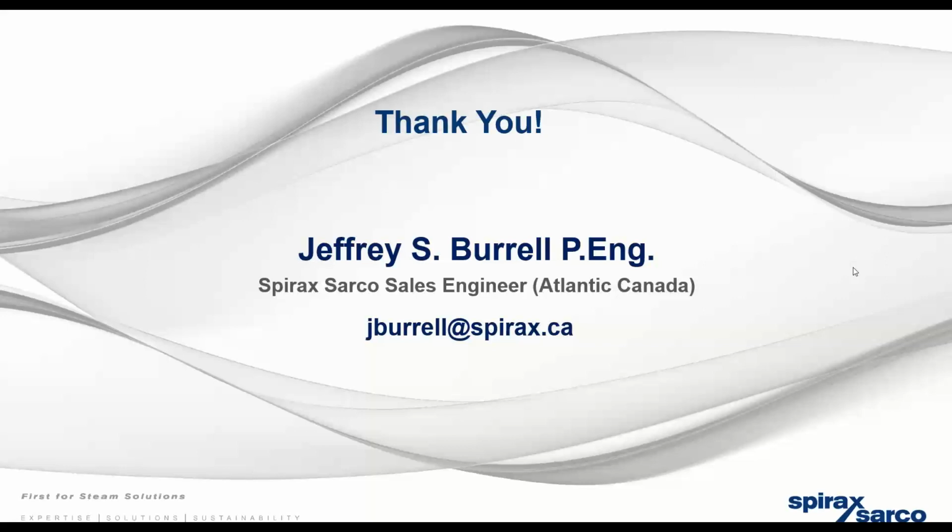Jeff, in your earlier comment, are you suggesting to insulate the condensate line? Absolutely. Yeah, I agree with Jeff. The hot condensate line, because if we look at it from an energy perspective alone, not a water hammer issue, hot condensate lines are, I use the term 0 psi steam lines, but they could be up to 10 psi steam lines, with very little water volumetrically. So they're basically the same as steam lines. Now, pumped condensate lines, should you insulate them? Yes. What's the radiant temperature off them? Very low. But hot condensate lines, yes, definitely need to be insulated.